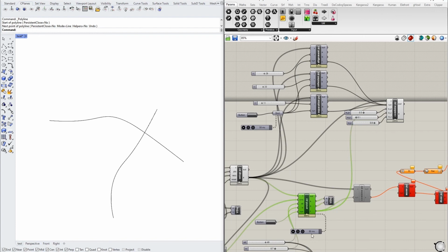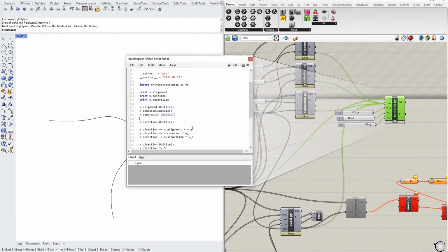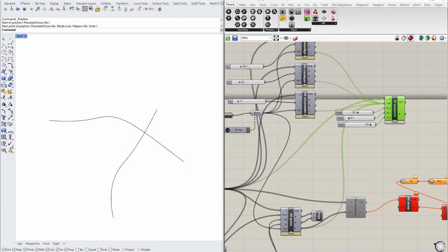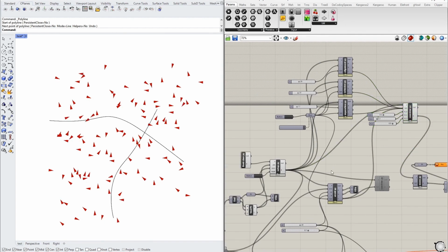And we don't need the trigger. We can connect the boolean here so that we can run all the processes when we click on the button or trigger it at specific time interval. And we will add the influence of the avoid vector within this combined node. Simply by adding this line here, direction plus equals, which is the shorthand for direction equals x direction plus x dot avoid. X is the Boid instance. We will use the shorthand for now. Right. And we will reconnect A with X. Now let's run it.